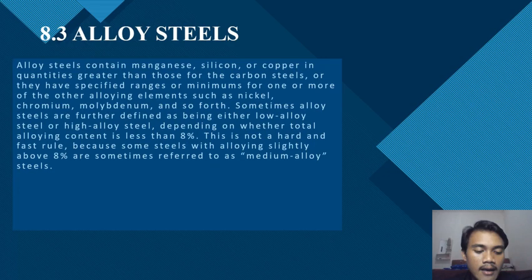The types of HSLA steel commonly used include weathering steel, designed to exhibit superior atmospheric corrosion resistance; control rolled steel, hot rolled according to a predetermined rolling schedule, designed to develop a highly deformed austenite structure that transforms to a very fine equiaxed ferrite structure on cooling; pearlite reduced steel, strengthened by very fine grained ferrite and precipitation hardening but with low carbon content, and therefore little or no pearlite in the microstructure; and microalloyed steel with very small additions, generally under 0.10% each, of such elements as niobium, vanadium, and or titanium for refinement of grain size and or precipitation hardening.